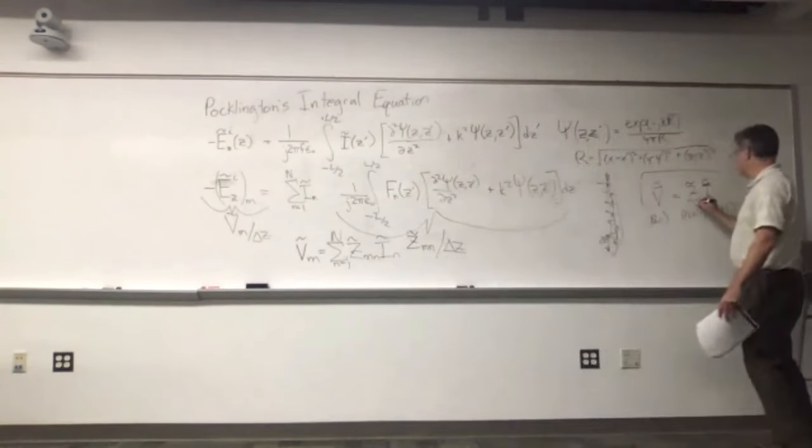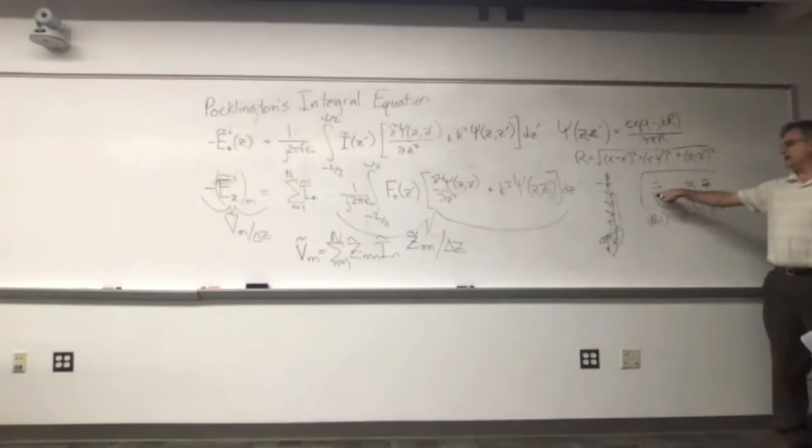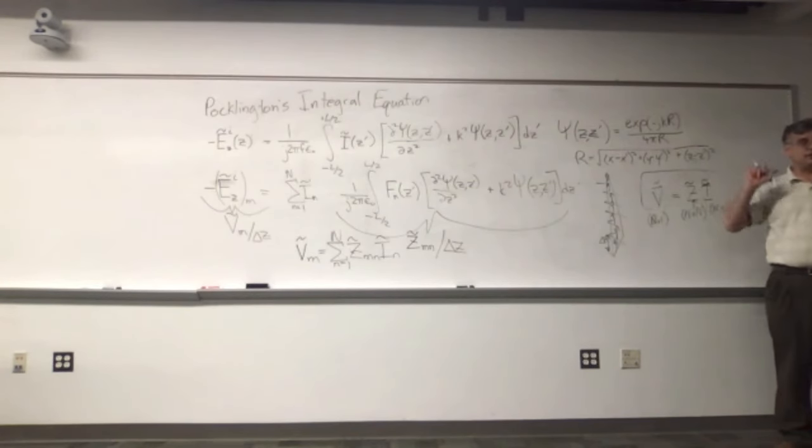You've calculated your Z. All you have to do is figure out, how am I going to excite this? Well, if it's a half-wave dipole, I'm going to take the center voltage. I'm going to put a voltage there, just like a transmission line would. And everything else I'm going to set equal to 0 volts, because I'm not going to put feeds on those other segments.